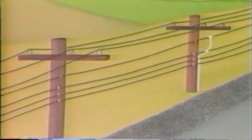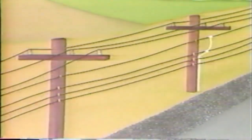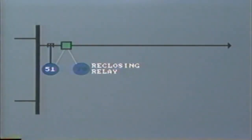Well, the vast majority of faults on overhead lines are due to lightning. The high voltage flashover to ground creates a flow of fault current which trips the breaker on overcurrent or perhaps overvoltage. However, the fault is only temporary in nature and will be removed as soon as the breaker trips. Therefore, when the breaker is reclosed by the reclosing relay, the fault will have disappeared and the line can continue operation as normal.